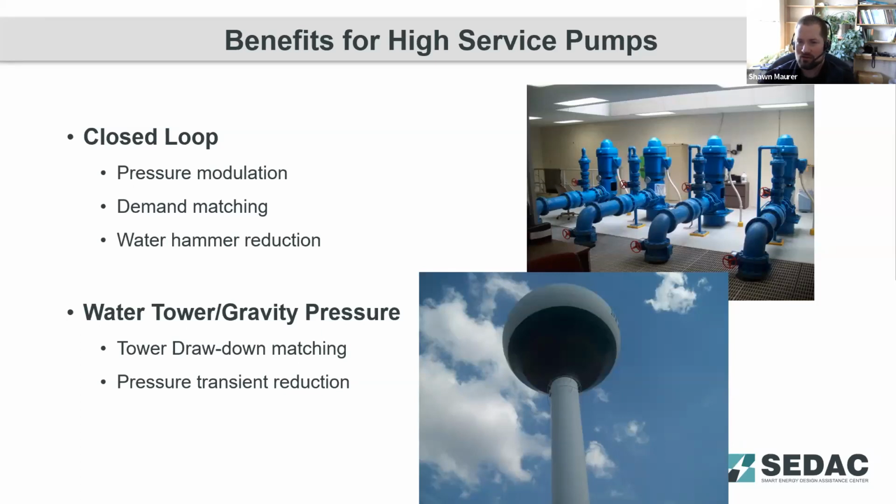And then also, if you've got system delivery pumps where at higher flow rates you use one pump, and at lower flow rates you use a smaller pump, the VFD can provide a smoother transition between those that, again, reduces those pressure transients, reduces that water hammer potential, reduces leaks in your system, and extends the longevity of your distribution network.